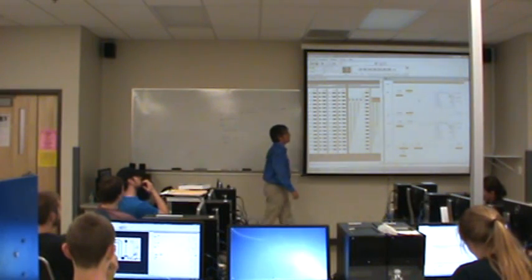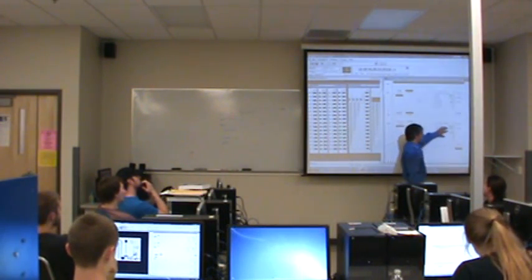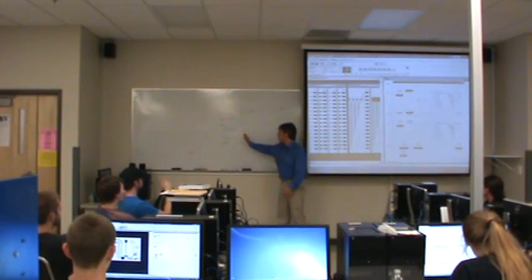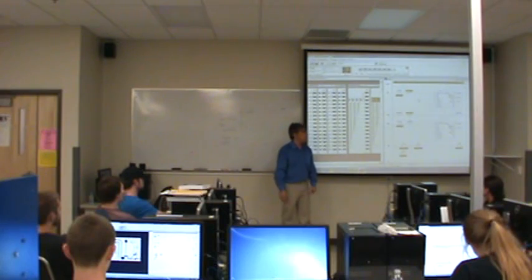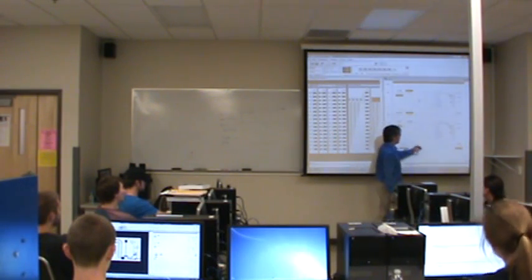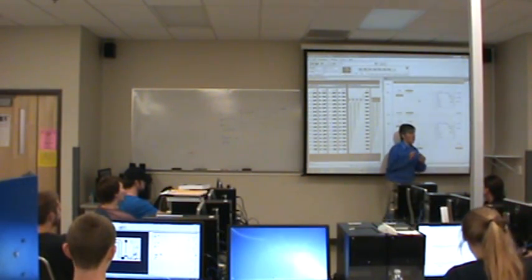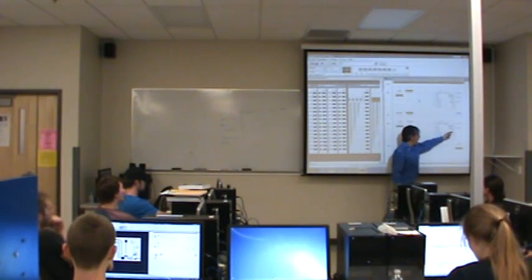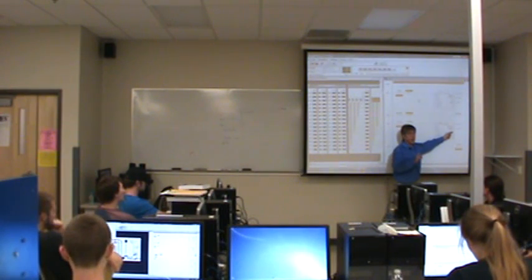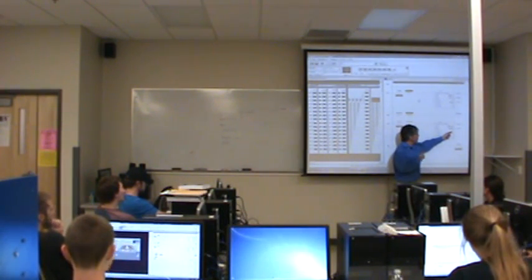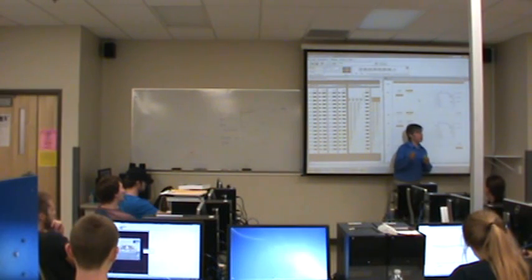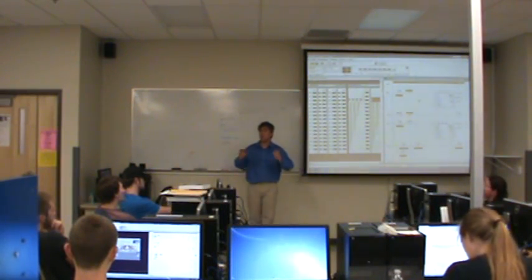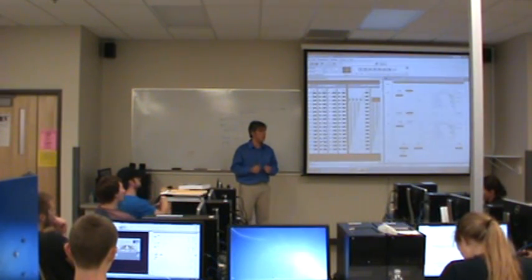Well, that's what the sequence output instruction is like. Now, the sequence output instruction has to have a list in memory somewhere of which outputs you want on, okay? Because what this thing does is it can turn on any of the outputs all at once that you want. Notice it's referencing output word 6. This is not referencing one particular bit. This instruction is able to turn on or off as many outputs as are in that word. So it can turn on or off 16 different outputs.